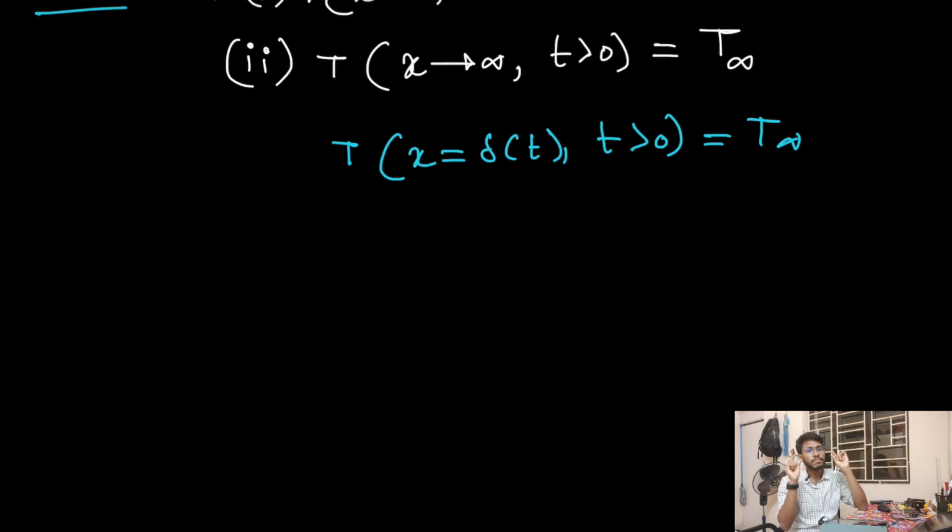If you have studied the boundary layer theory, then you can make the analogy there: the boundary layer thickness is an imaginary thickness. It is taken as the thickness at which we get the velocity equal to 0.99 times u infinity, the free stream velocity.